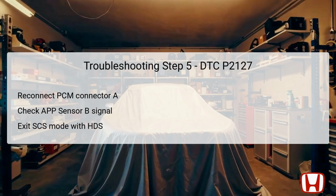Start by removing the jumper wire from the APP sensor 6P connector, and then reconnect the PCM connector A. Next, connect a jumper wire between terminal A of terminal number 1 on the APP sensor 6P connector and terminal B of terminal number 3 on the same connector. After setting up this connection, exit the SCS mode using the Honda Diagnostic system.